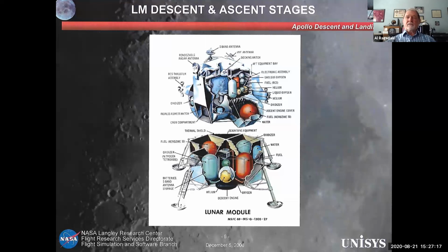It made for an interesting ride during the liftoff. It would rise until it was going upward at 50 feet per second and then pitch down 45 degrees, which gave you the impression, from flying an airplane, that you were about to dive back into the ground. With all the RCS jet thrusters, it had to stay within a dead band of some attitude. If you got outside the dead band, a jet would fire to move, and once you got back inside the dead band, it would fire again.